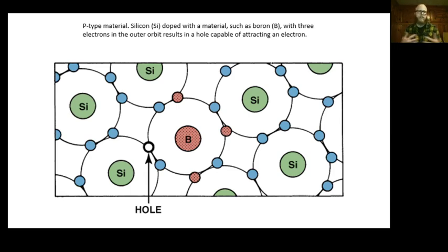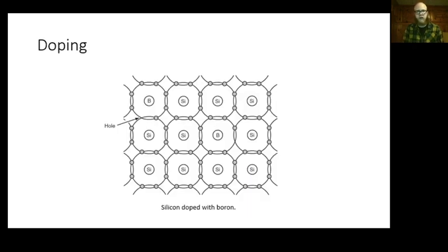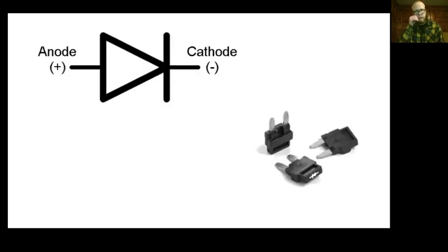So having this doped situation where my N-type has an extra electron, my P-type is missing an electron, well, you can kind of see the Romeo and Juliet story that's about to take place. And there we are. We're just seeing in the lattice that we're missing an electron. And they call that holes. Okay? So N-type has an extra electron, and P-type has a hole, a slot in which that electron could fit if we get things oriented the right way.